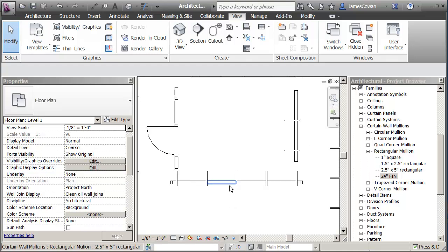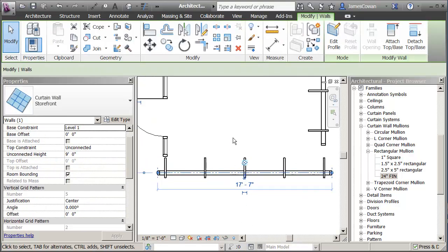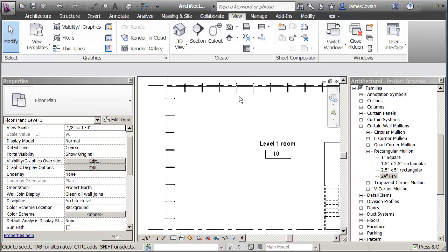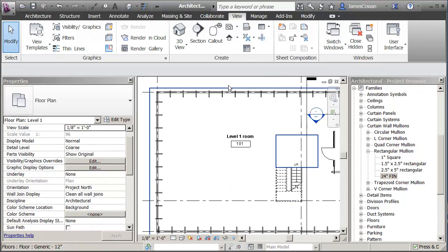You won't have a case where in some places the curtain walls are being moved in, and in other places they appear to be being moved out, because you don't have a flip symbol here to flip it over. You can do it with the space bar, but you don't want to have to go around all the walls of your building that are using this setup. You want to be sure that each of them knows what is outside and what is inside.